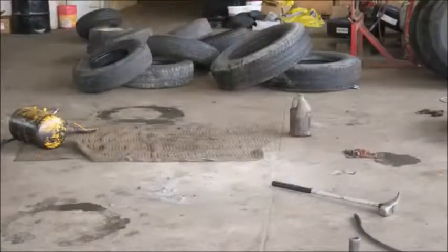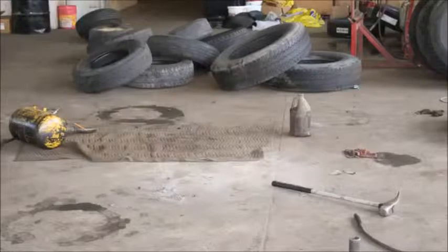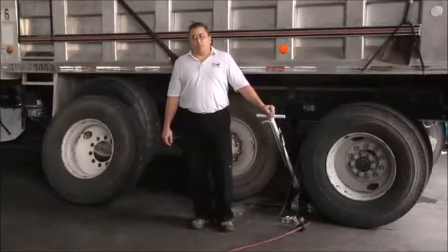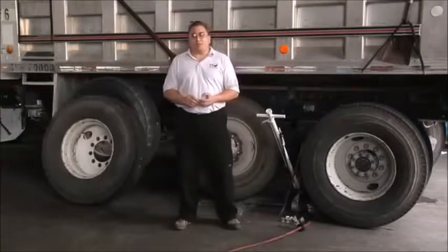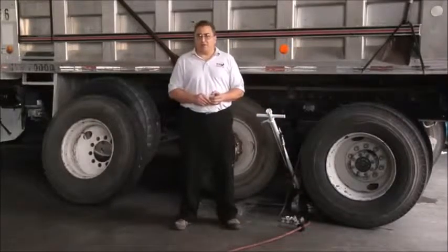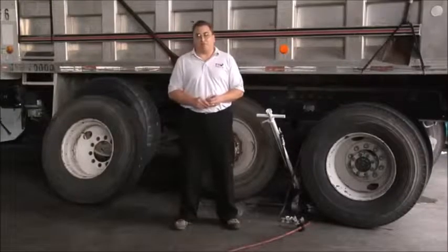In this example, the tools and tires on the ground are obvious hazards, so they should be properly stored when not in use. And even though the blanket is necessary to protect wheel mating surfaces, it creates a serious trip and fall hazard when it's left on the floor in the work area. Housekeeping plays an important role in tire shop safety. Most slip, trip, and fall accidents can be prevented if spills are immediately cleaned up and areas with a lot of foot traffic are kept reasonably clean and free of obstacles.